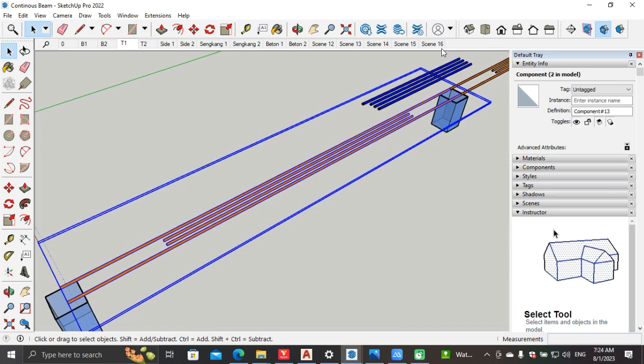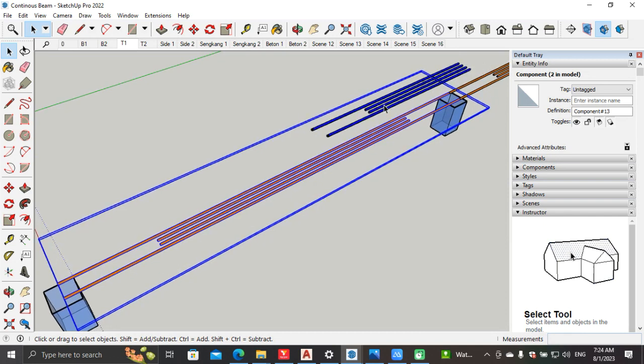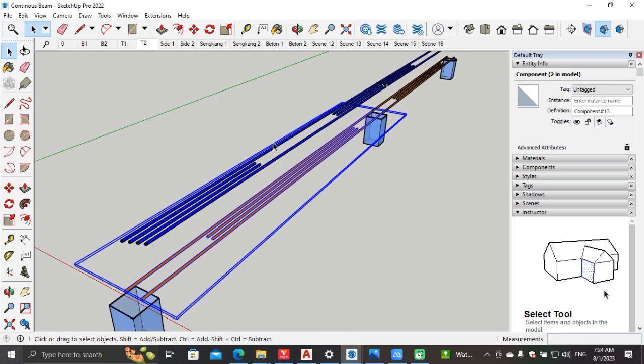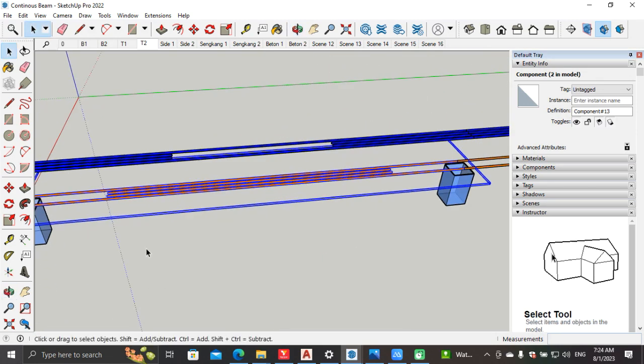And in the top also, towards the support, we need 4 number of bars. If it is 3, you can give it as 3, and the remaining 2 will be given to continue the cage structure, or else you can give 4 numbers throughout the section, but it will be expensive, not economic. So we will be giving some curtailment. For example, if we are using 20 mm bars and all, it will be expensive. So this is the case.